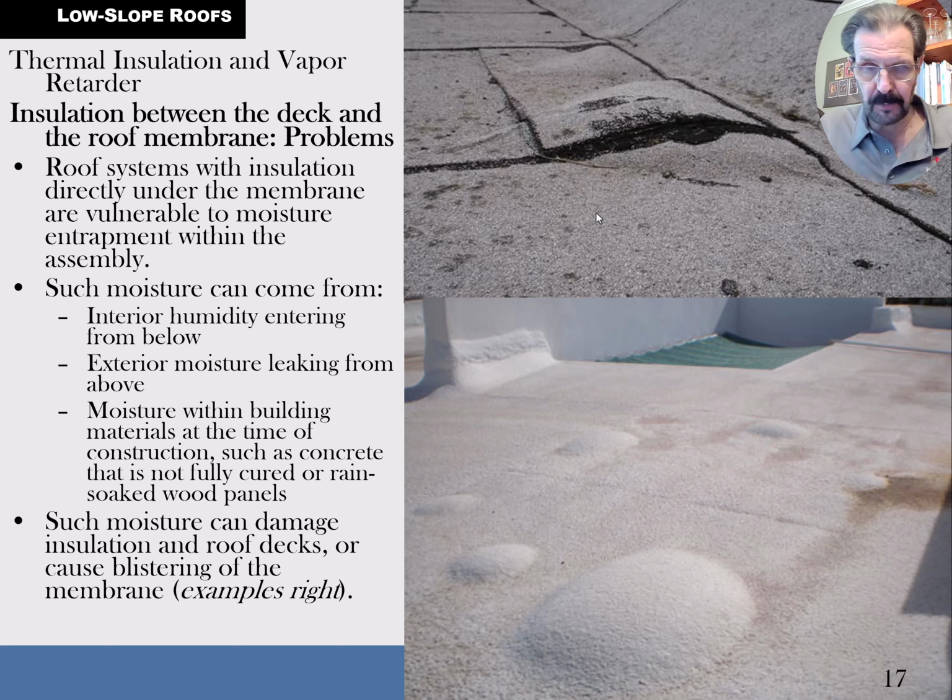And so oftentimes the problem with this inverted roof is you can have enough space in there where moisture can still get in, and if it can, it's going to get very hot, and it can create these little blisters. So if you're ever walking on a roof, be careful about flaws like what you see up top here, where my cursor is squiggling around, or down here where you see these domes. They're blisters, both of them.